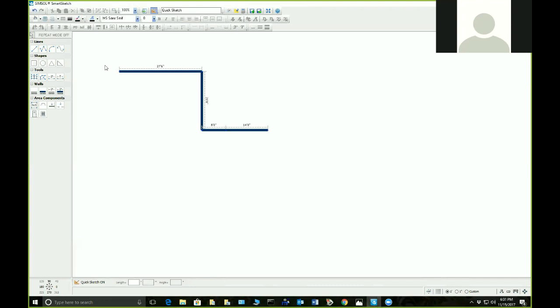So as I put the dimension in, it segments it out, so I could say, okay, my entrance starts at 8, and then I'm going to go to 14. Now, from here, I can go down to, for example, 17.9, 17 space 9. So as you can see, I'm putting it in and then hitting my down arrow. And if I want to continue that on, I can then put in, for example, 6.